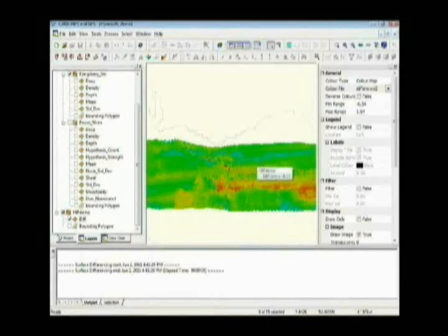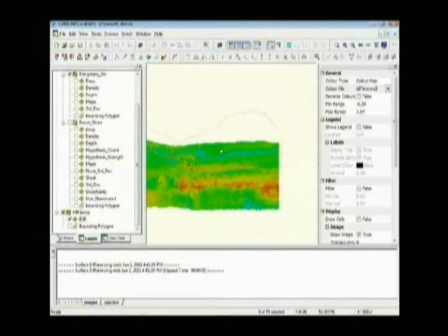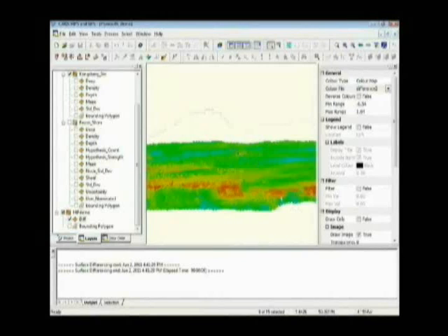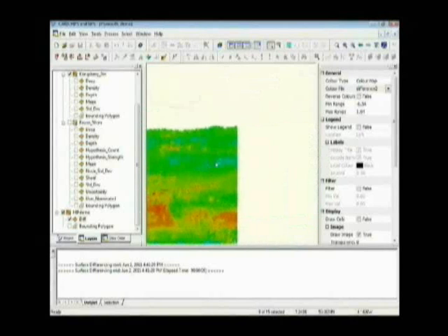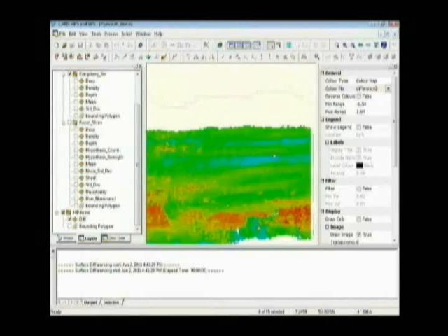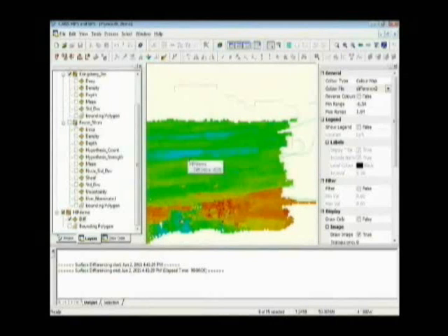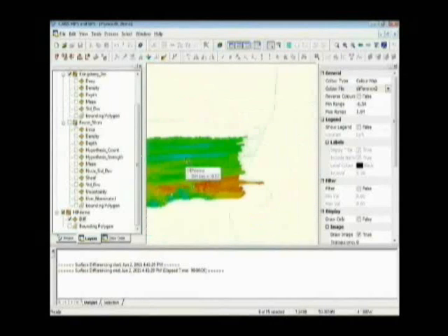Well, Josh, one of the first things I like to do when I've done a hydrographic survey is to run a comparison with the previous survey just to see how the two agree. So, what this can sometimes highlight is the area of red that we've got there. Maybe we've got something wrong with the tide if that's all associated with one line. It also could be showing some errors in our sound velocity data, or maybe there's just some bad soundings in one of the data sets.